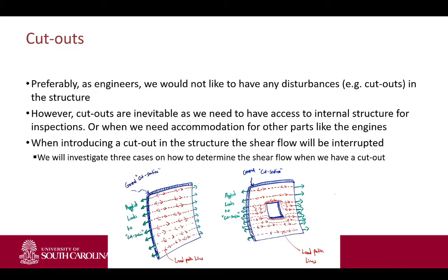Basically, if you have any crack propagation, say you have a panel, and there's a cutout here in the middle, the stress concentration will be the highest on the sides. You have a uniaxial loading, so basically you create a crack propagation near the side of the panel.